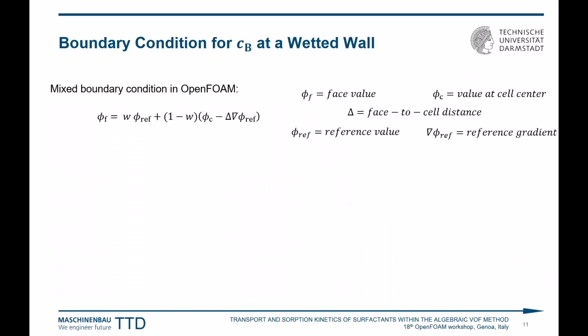And just for the interest of this audience, this boundary condition at the wall, as I mentioned, is implemented using a mixed boundary condition. All this is developed in the interFoam solver, and then we extended it using different libraries for contact line dynamics, adsorption dynamics, and everything. It's an open source library that we are going to publish. Using this mixed boundary condition in OpenFOAM, we have modified our boundary condition. For example, as I said, the net diffusion should be equal to the rate of adsorption.